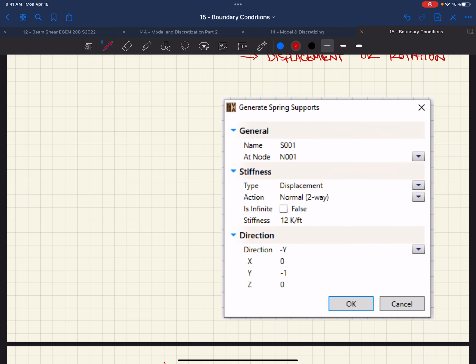Okay. Let's look at live load reduction as well. VA can incorporate that, yeah. And if you want to incorporate that in that model, it may or may not already be incorporated, right? It's up to you. Okay. But if you do incorporate it, tell me why, or why not you would want to incorporate that. Okay. Live load reduction, yeah, beautiful, right?